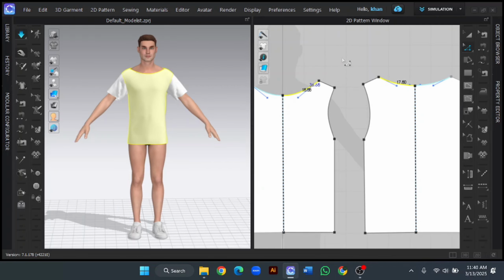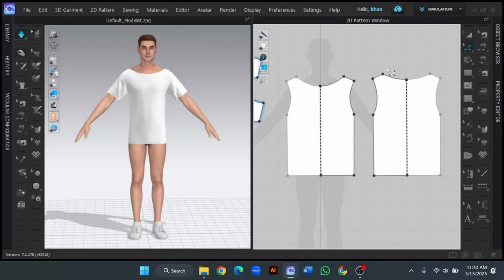That's because we are just making the measurement of the half necks of both sides. Okay, now we will simply click these two buttons, or just one button, and we can reduce the neck size because I think it's too large. Okay, I think now it's okay, and we can do this for the front one as well.